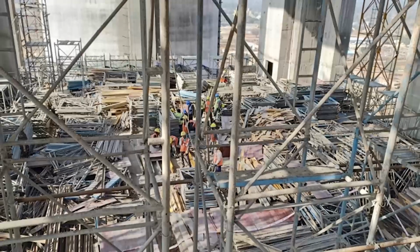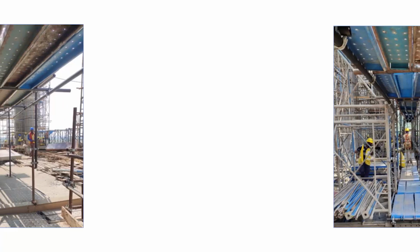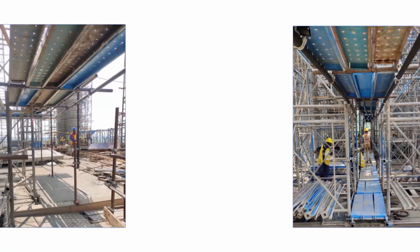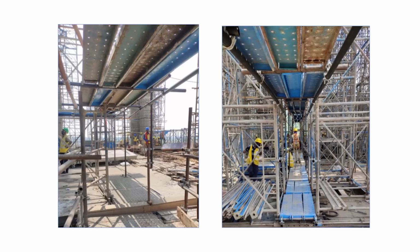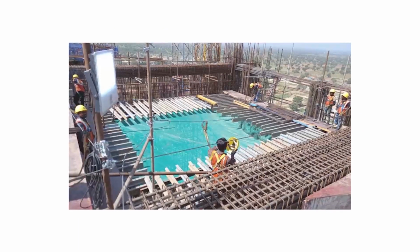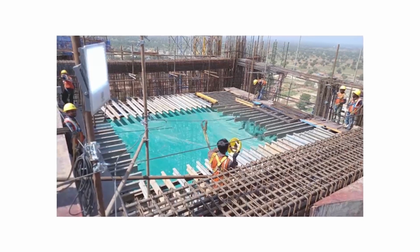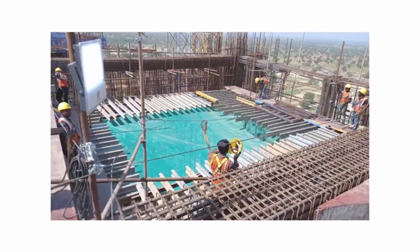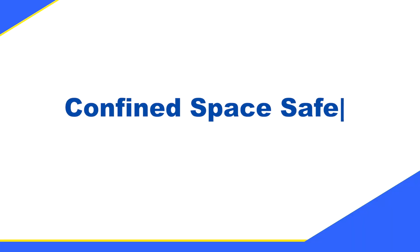While erecting the form work towers, materials may fall on the workers working on the same floor itself. So, we need to keep materials that are necessary for the day's work and remove all the loose materials. At beam bottom level, we need to tie safety net between beam to beam so that falling materials during beam construction will be captured. Confined space safety.